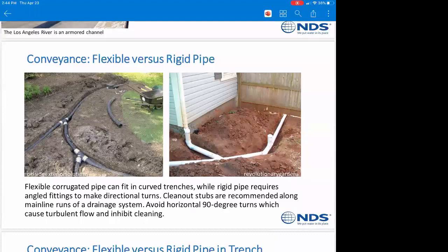They're not very durable. It's not a very long-term solution. And in terms of moving water, they just don't move water at the same rate that PVC does. If you're not using PVC to do drainage, at least consider it, because the performance of PVC versus flexible pipe is night and day. And we're going to get into that in a table here that we're going to pull up.